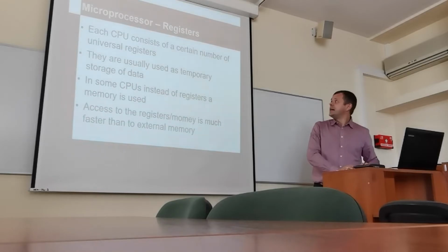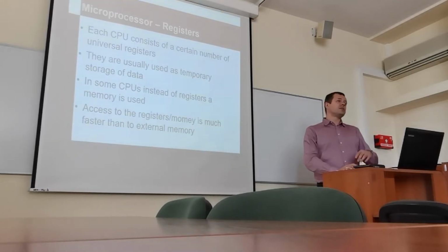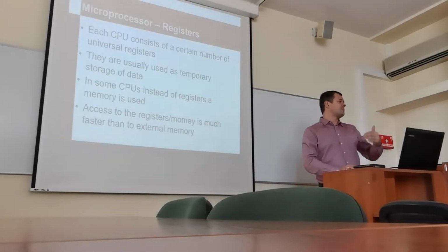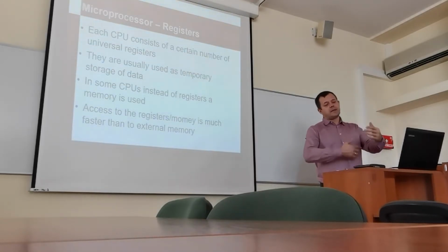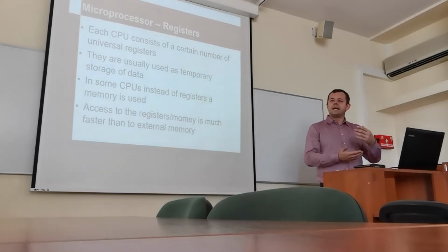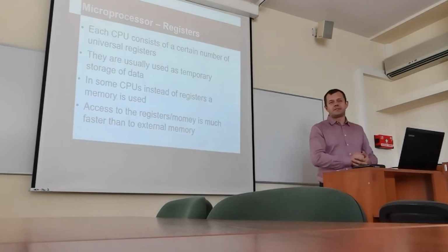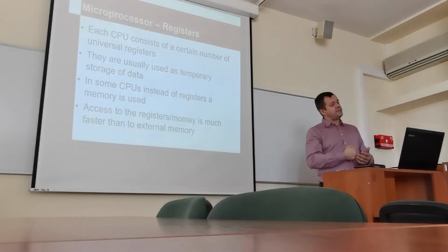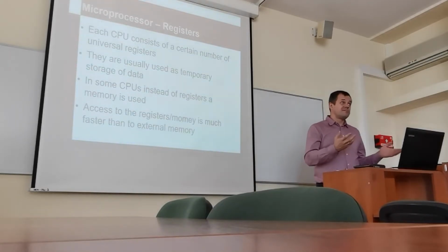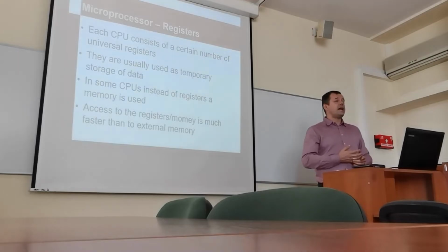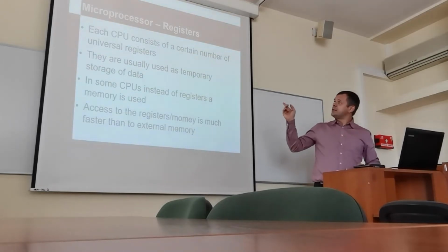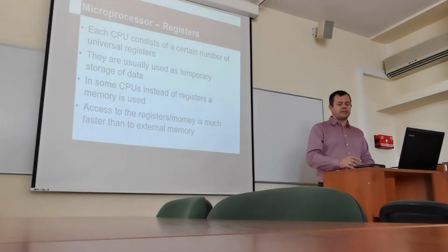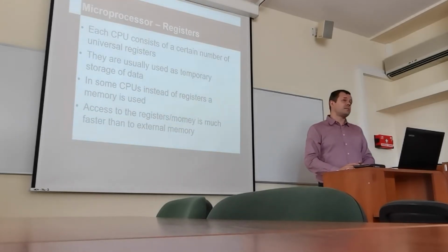The best for LIFO is sequential access, so that we put on the stack a sequence of data and then get back from the stack a sequence of data. In case of registers, it's better for random access. So it's better for random access, and as well for random access, because it is inherited, the so-called inherent addressing modes are used to access the registers.